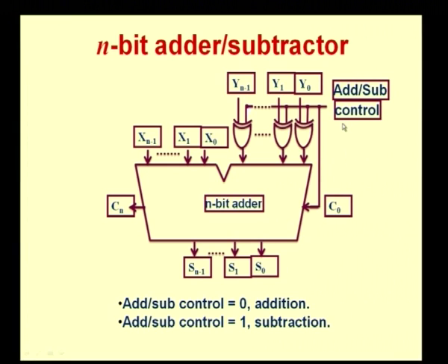Okay. So, let us see how this will do both addition and subtraction now with the help of this control circuit. So, once I have this control here with a value of 0 given as the input, when I give 0 as one of the inputs to an exclusive OR gate, the output of the exclusive OR gate will just depend on the other input. So, if I have a 0 here, the output will be 0. If it is a 1 here, it will be a 1 here. That is, if one input is 0, it will just pass the other input to the output, which is what I want, right. Because I want to do an addition, I just want my x's and my y's as direct input to the n bit adder, and I also want my C naught value to be 0. Now, since for an addition operation this control signal will be set to 0, this control is what is coming as input over here. So, C naught will be equal to 0, right,